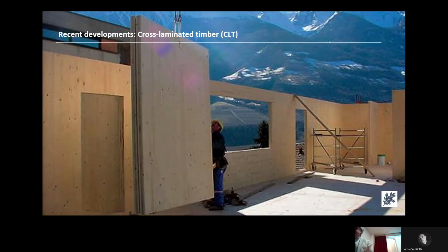Essentially, if you imagine plywood, using thin veneers and using the cross grain to make a thin panel, CLT just takes that a step forward and uses lamellas about 20mm thick to make panels either 3-ply, 60mm, 5-ply, 100mm or 7-ply. So you can make large rigid panels for floors, ceilings and walls.